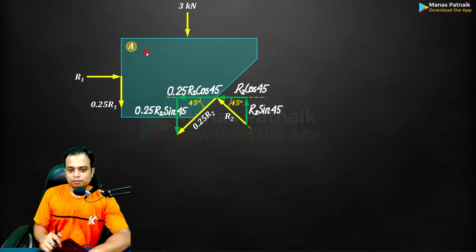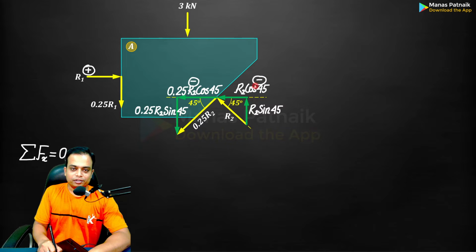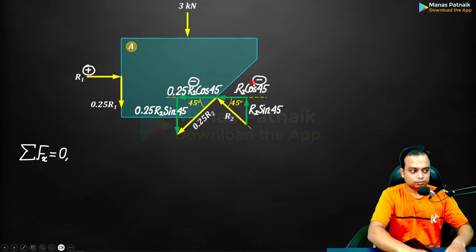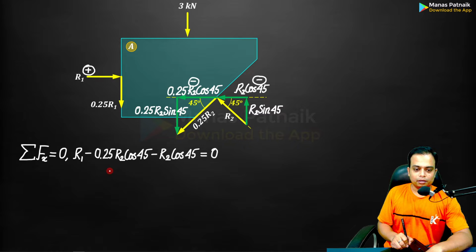Now let me start with summation Fx equals 0. If you watch, R1 is to the right. That's why positive. R2, this force and this force, both of them are to the left. That's why negative. Is there any other horizontal force? No, sir. None. So just write them down with their proper signs. Now you can simplify for R2. R1 will be equal to 0.88 R2. We are going to be using this result.